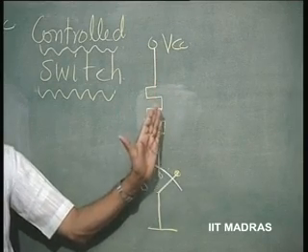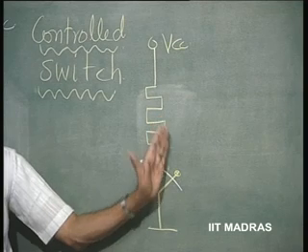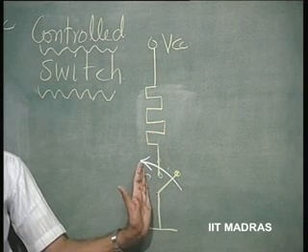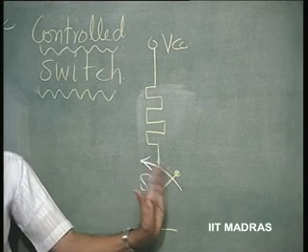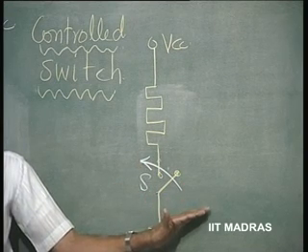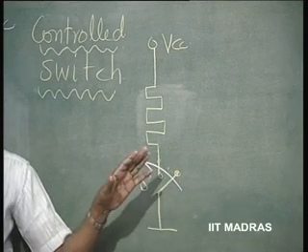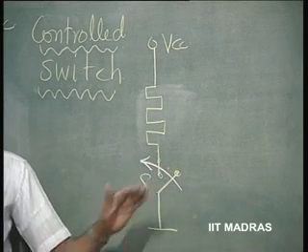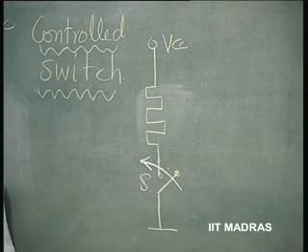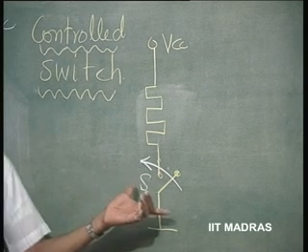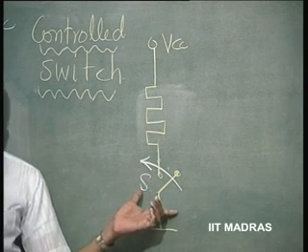I want to heat the heater element by connecting the power, and as soon as I reach the temperature, I want to disconnect the power, and again I will connect it, again disconnect it. I might control in this manner, connect it and disconnect it, so that the temperature rises up to a point and keeps on remaining around that point. So, this is an on off controlling system like our fridge.